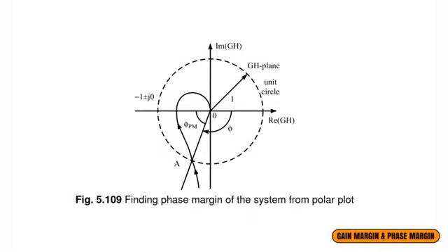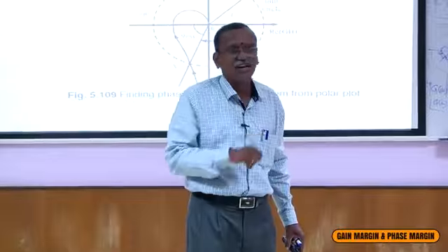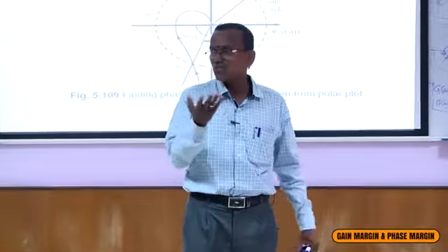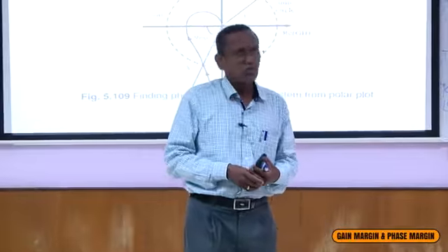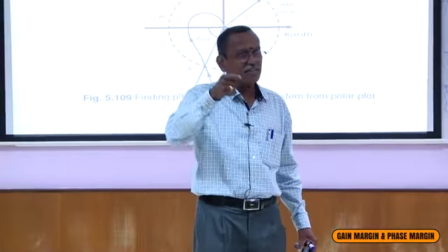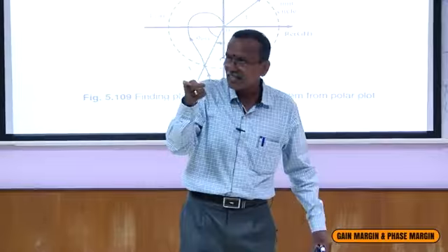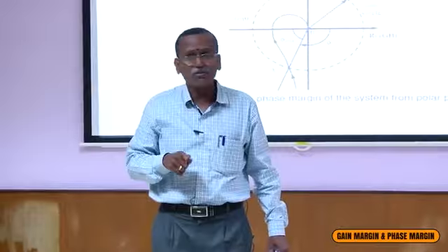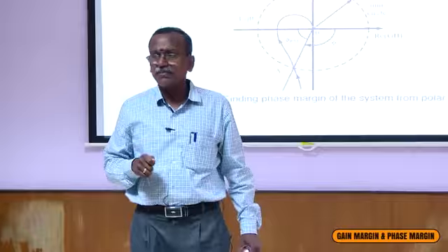But instead of changing K, I have a facility. If I change some particular component, there will be a change in phase shift only. Let us assume there is no change in K. But if I adjust some part of the system, there will be a change in phase shift. For example, in an RC phase shift oscillator, if I change some capacitor value in the RC component, there will be a change in phase shift. So without changing gain, I can adjust phase shift.